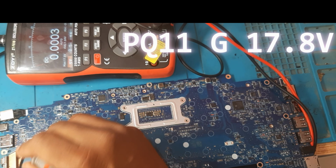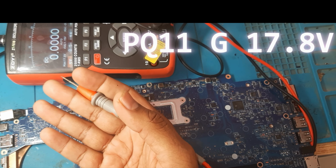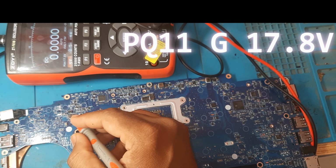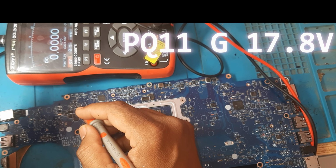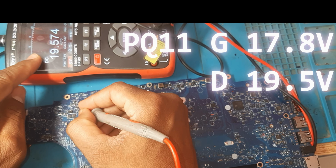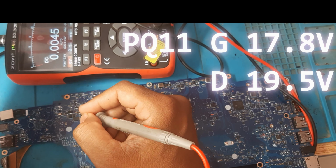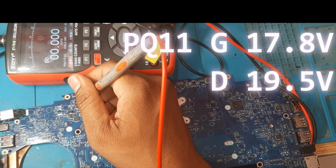It means in case the voltage divider happens, approximately according to the voltage divider, 3 or 4 or 1, whatever it may be, that voltage should come to the drain. But here we are getting 19.5 volts, correct? That should be here then, 19.5 volts. Then what about the source? The source also 19.5 volts, correct? That's directly the supply. It's coming only from the supply.